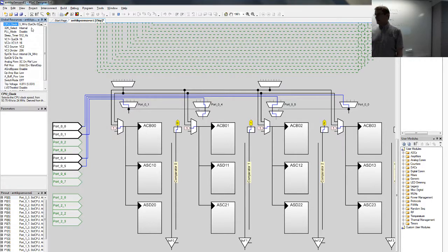For debugging or developing you would use your internal clock, and then for the real device you would buy that 2-cent crystal to run the real-time clock. Okay.